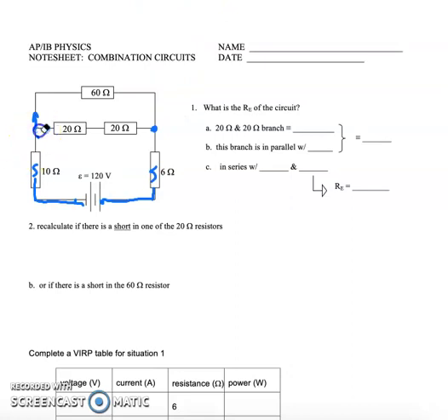All right, so let's figure out the effective resistance of the whole circuit. In other words, we've got a 10, a 6, two 20s, and a 60. What does it quote unquote total up to? And it's not going to be the sum of those. Well, the basic approach is to take everything that's in series with the battery and simply add them. So we know that the resistance is going to be 10 plus 6 plus the contribution of these three. So it's going to be at least 16. And as I said earlier, these three are in a parallel branch, but they're in series with these two. In other words, if I can take these three, reduce them to one resistor, one resistance, and I connect it like that, then I have a series circuit. Okay, so that's the idea.